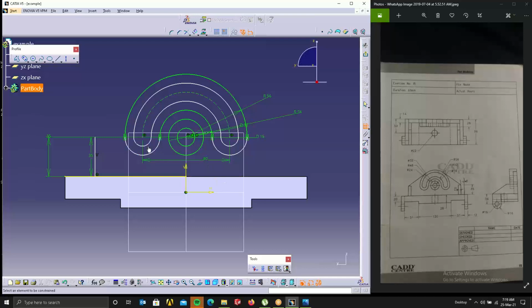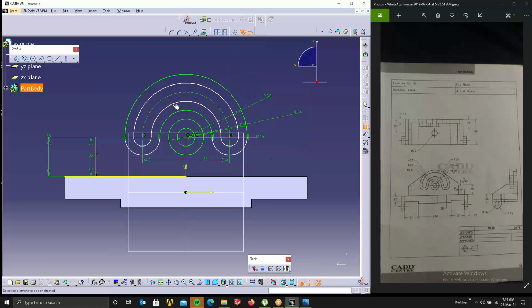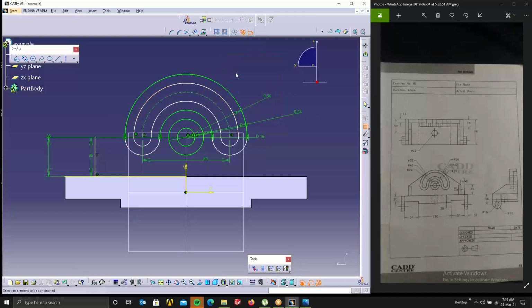Okay, so concentricity, and now we just have to move and see where it is going wrong. So just select vertical. Yeah, vertical, nothing will be constrained. So it's not. Oh, it's over constrained. Just try moving it. All that you need is just try moving this.